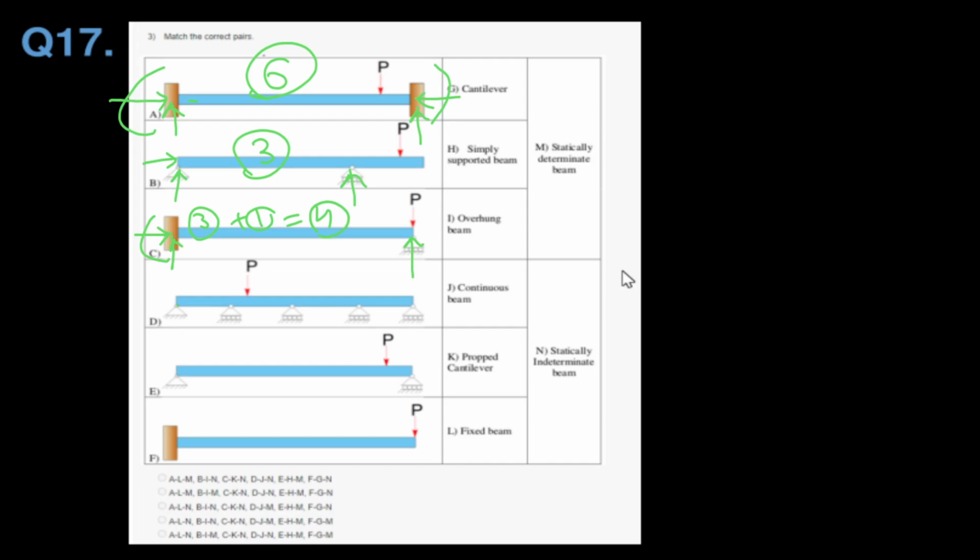so here is a continuous beam, number of support hinge, it will give a horizontal as well as vertical. Here is a roller, will give only vertical. Here is a roller, will give only vertical. Here is a roller, only give vertical. So here is 2 hinge, then roller, 4 roller, 2 plus 4, there is 6 reactions.